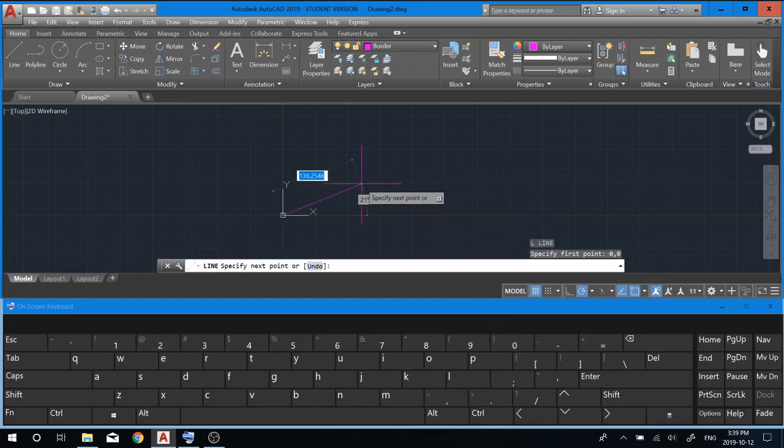And you can see it automatically puts the beginning of my line at 0,0. Now, when you're new to AutoCAD, it's very tempting to click and use the mouse buttons a lot. We're going to use the mouse for aiming our line, but we're not actually going to click the mouse keys. We're going to use spacebar. All right, so what I'm going to do for the rest of my lines is give my line a direction with the mouse.